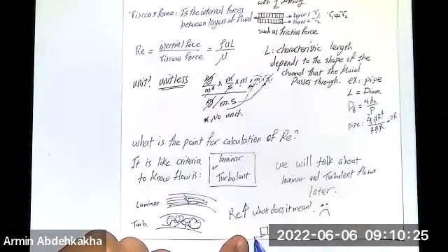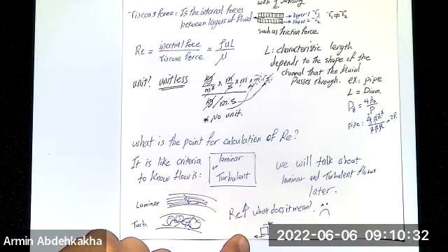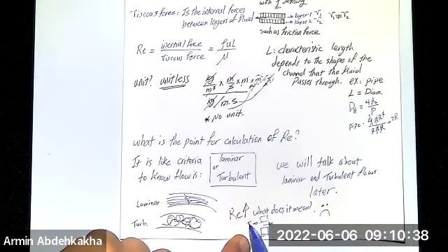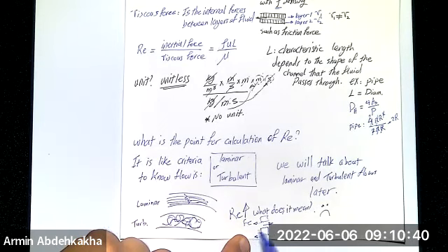The below one is going to give you viscous force in this way, and the top layer is going to give you another force here, because this layer is going to give the top layer a force of F tau in this way. And based on Newton's law, you have another force in this direction. Then you have two forces that give you a clockwise rotation on this box of fluid, right?